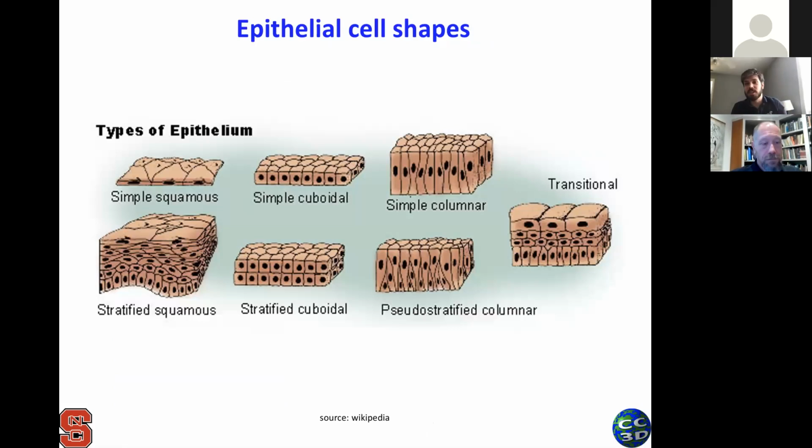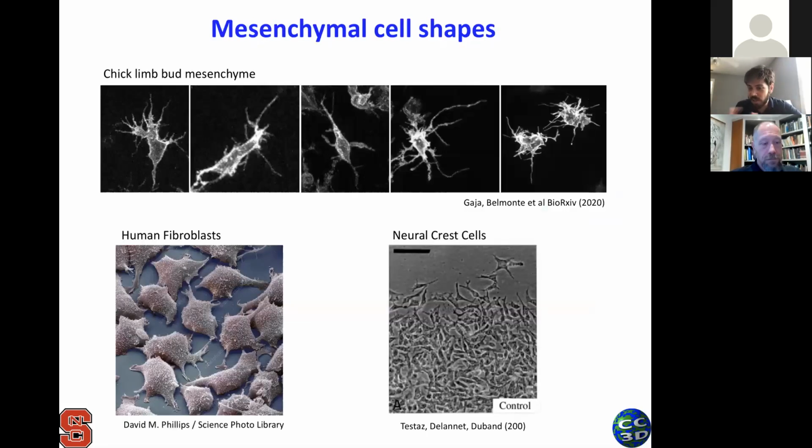And then if you look at this and look at what you had before, many different cell shapes. And the question is, if you have a specific cell in mind that you would like to model in CompuCell, how can I tune my parameters to make the cells look more like this or more like this? I already tell you that it's very hard to make those cells look like this in CompuCell. You will need a lot of pixels. You probably need to actually break your cells into small compartments. But there are things that can be done. And the idea of this module is to show all the parameters, or the basic parameters in CompuCell, that can actually have an influence on the shape of the cells.